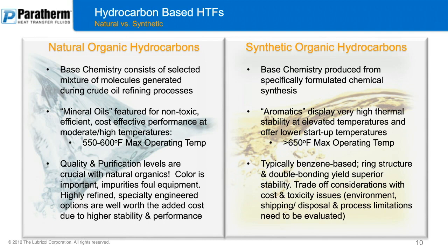Now, moving into the synthetic organic hydrocarbons, also referred to more commonly as aromatic-based fluids. These are where a base chemistry will be produced from specifically formulated chemical synthesis. So you have a target that you're trying to synthesize through a chemical process, and it can meet certain criteria or performance levels that you're looking for. So aromatics are typically going to be benzene-based. They display a very high thermal stability at higher temperatures, and then also offer lower startup temperatures, more so than the natural mineral oils will.